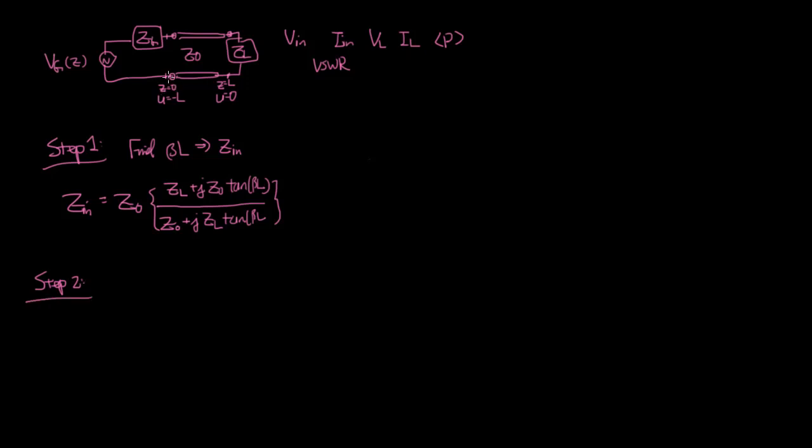So that is going to give you the impedance over here, and then you can use it in the same manner that you were using Z naught in the case of the time domain calculations. So the voltage going in, or in other words, the voltage at z equals minus L, is going to be equal to the voltage divider between ZG and the input impedance.